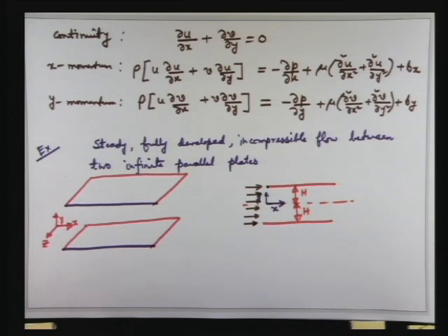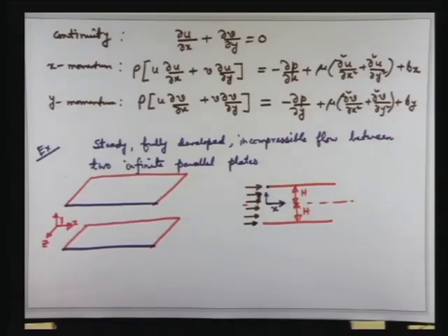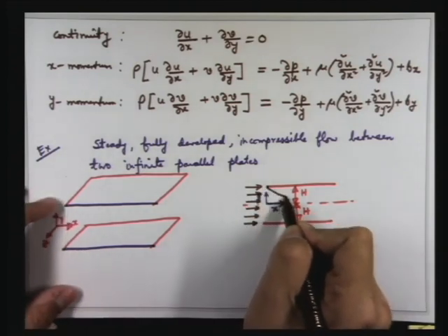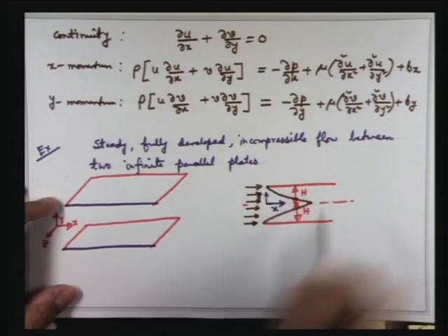The only difference is that, there are many differences. One important difference is that you have boundary layers growing from the two sides here, from the two plates, whereas for one plate the boundary layer grows on one side and there is an infinite free stream on the other side. So the boundary layer grows from here and the boundary layer grows from here.